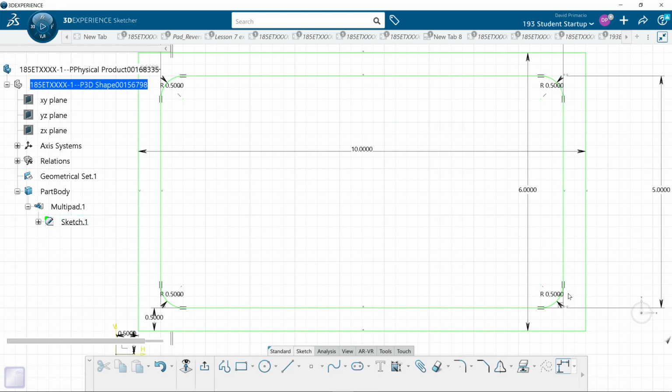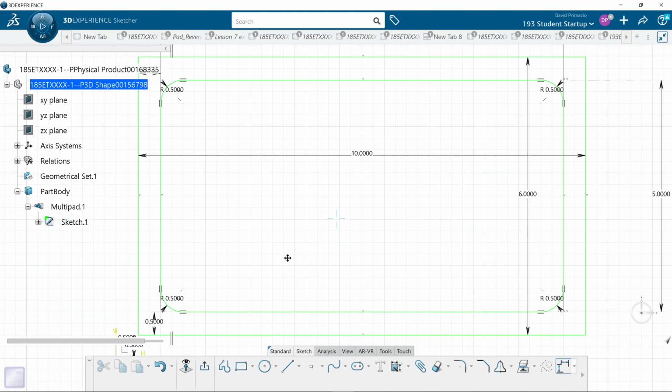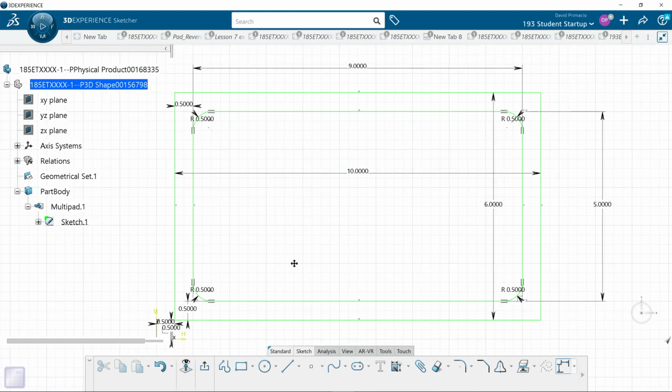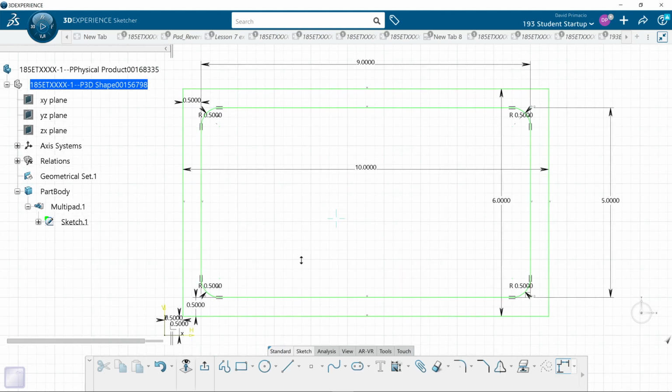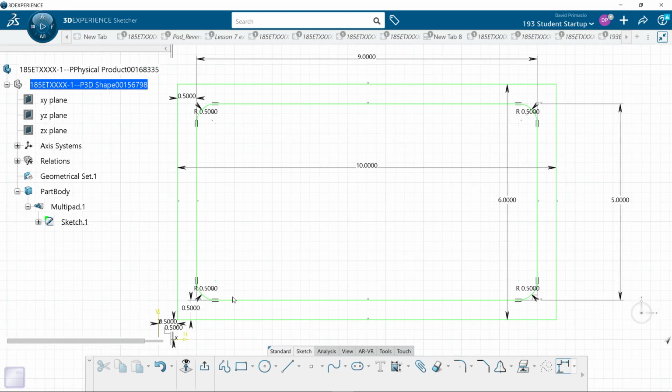And then, are they tangent? Is this curve and this line tangent? Yes. Well, that is all correct. So a lot of times you'll hear people say you have to have adjacent and tangency in order for us to machine this. So great. It is all looking like it will line up perfect. So I'm going to use a 1/2 inch cutter. Sorry, a 1-inch cutter.